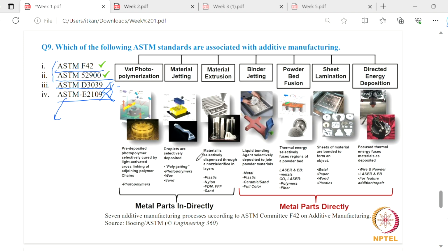Instead of a laser, I can also use a printer, like the ones used in DLP, which prints the whole layer in one go. That will be faster compared to the laser. The process is the same, but it is also known as vat photopolymerization.